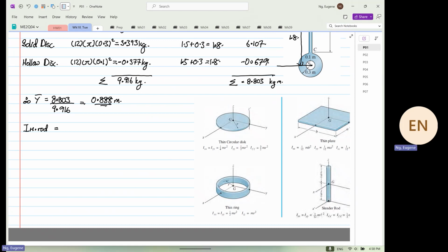Second moment of inertia is meter to the power 4. Okay, so that is the difference. When we say mass moment of inertia, we want to see how the mass will resist angular acceleration. Later you will see that. When you learn second moment of area, like what I talked about in the class last week, it is the resistance to what? Bending. Two very different things, but the symbol is the same, where they still use I. Okay, it is still I.